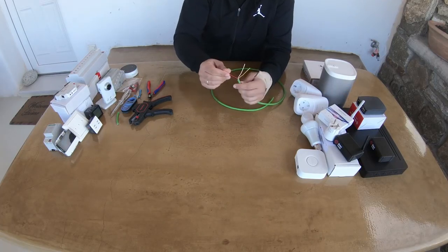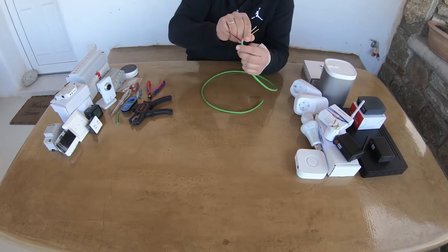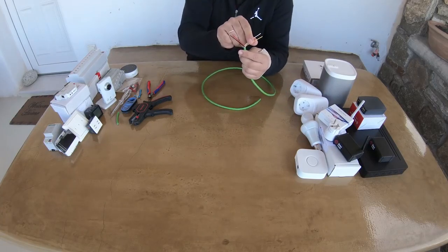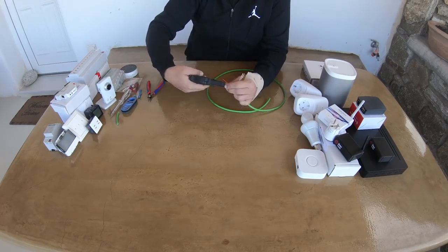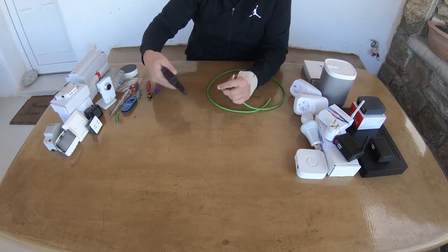As you can see, there is a red and black cable that are used in all KNX connections and a yellow and white cable that can be used, for example, in order to supply a KNX device with additional external power.